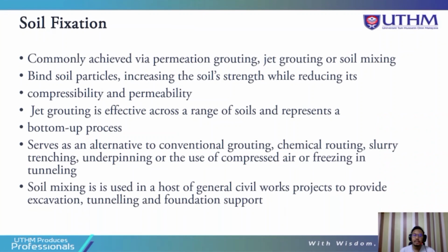Soil fixation is commonly achieved via permeation grouting, jet grouting or soil mixing. This binds soil particles, increasing the soil strength while reducing its compressibility and permeability.